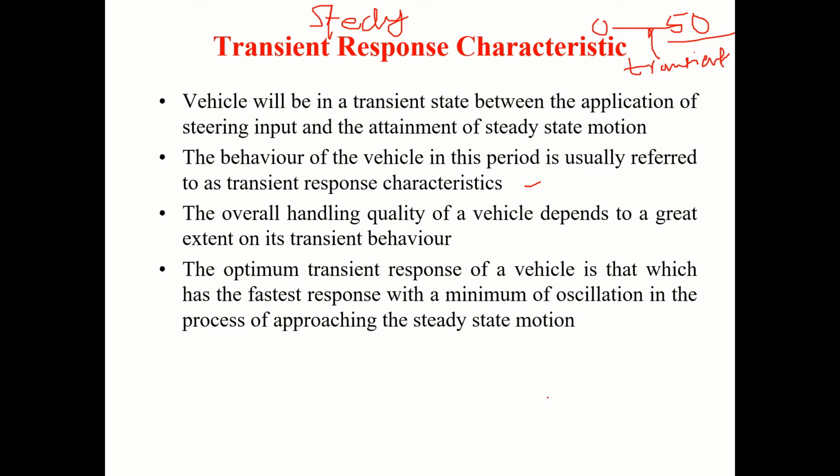So, something like this. Assume that I am driving the vehicle, then I am entering into a corner. I'll be coming with a speed of something like 100 kilometers per hour. By the time I enter here, I may come down to something like 60 kilometers per hour. Correct? So, in this region. After that, I'll maintain constant 60 kilometers per hour and the radius is also constant.